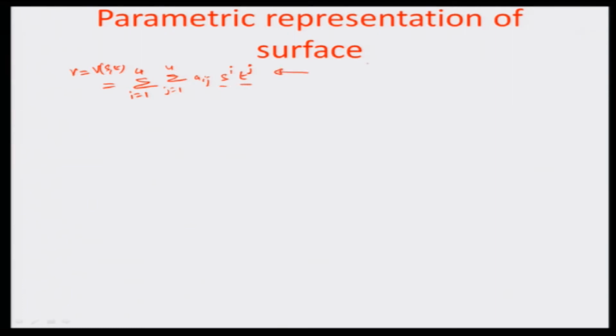If I compare it with what we had done before, we were talking about a case when we represented just one parameter. We talked about the point V as a function of t, and we defined a cubic polynomial a0 plus a1 t plus a2 t square plus a3 t cube. So this was a two dimensional curve case. Now we have a surface case. So this t has another parameter s introduced, and just as you had an index order i equal to 0, 1, 2 and 3, in this case we will have one index order for t and the other for s, because now it is a multiplication between s and t. So we are talking about V(S,T).